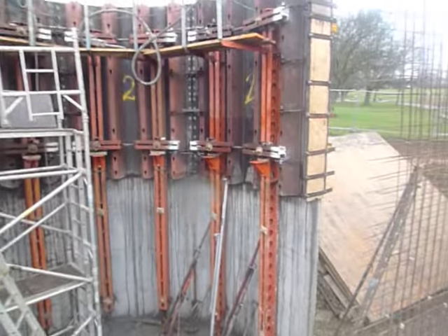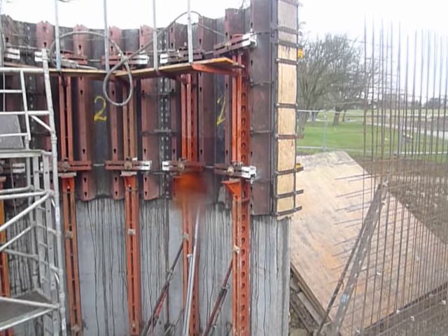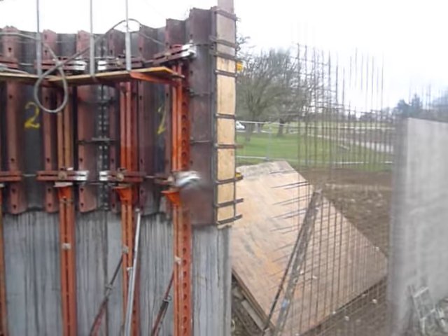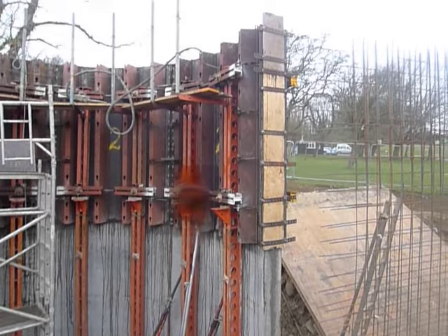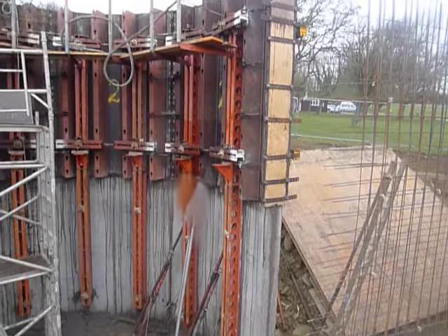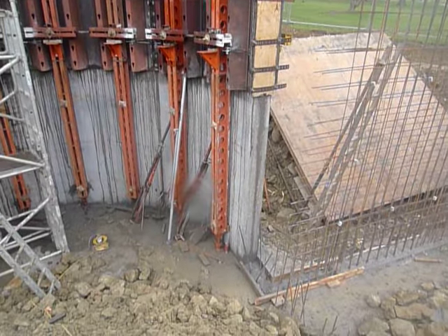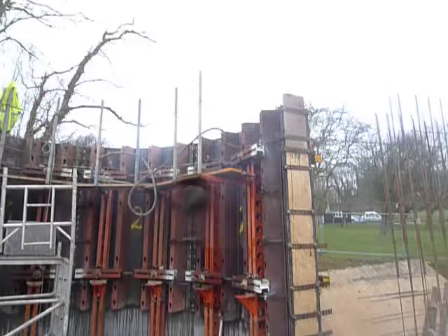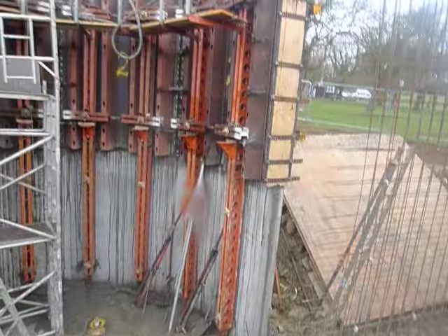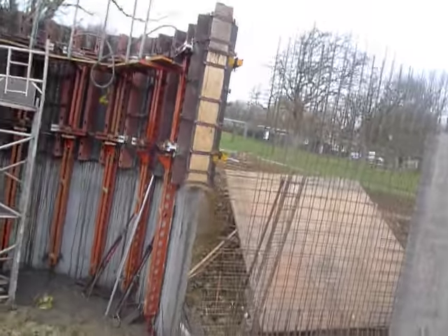And the way of controlling the in and out movement, let's take a step back. The movement works a little bit like it's at the kicker level. We have a point where the shutter is fixed there. So if you pull out at the bottom, it pushes in at the top and vice versa, much like a seesaw. So it's a case of pulling out the bottom strong back, and then the top of the shutter will go outwards, or if you pull it in, it goes inwards. And the ideal dimension for it to be right is 50mm. So we go to the bottom here.